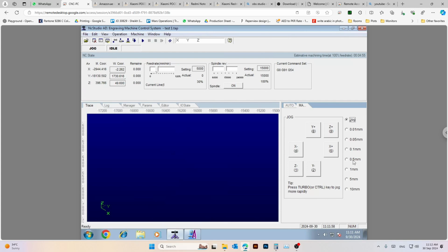Okay, when the bit is running, you cannot break it by pushing it down, because it will make a hole there already. It will drill there. So especially you need to select small precisions to move the spindle. Okay, so these are the main settings here.